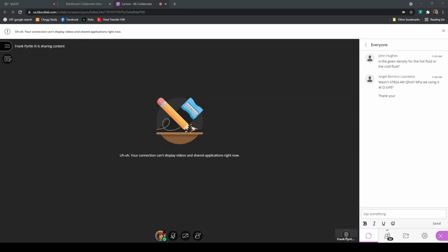Now, for shorthand, there's a lowercase c that's defined. It's not a specific heat. This is just a ratio of the capacity rates, the minimum capacity rate divided by the maximum capacity rate. This value will always be 1 or less than 1. If the two capacity rates are exactly the same, you'll get c equal to 1. There's only two capacity rates, one for the hot fluid and one for the cold fluid. The lower of the two is C min, the higher of the two is C max. So we define this expression.